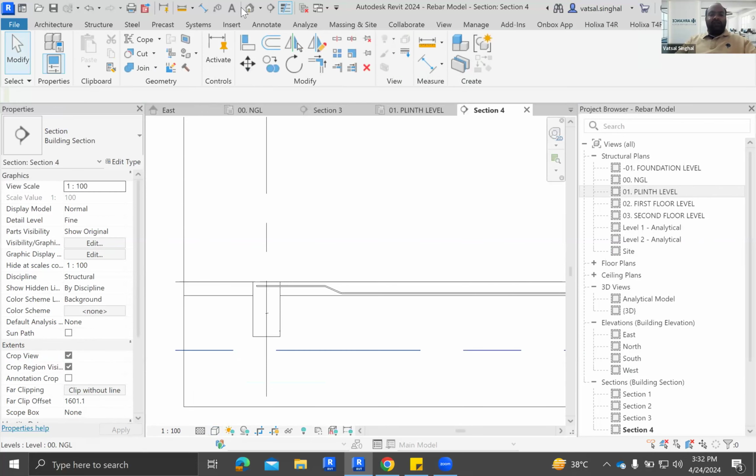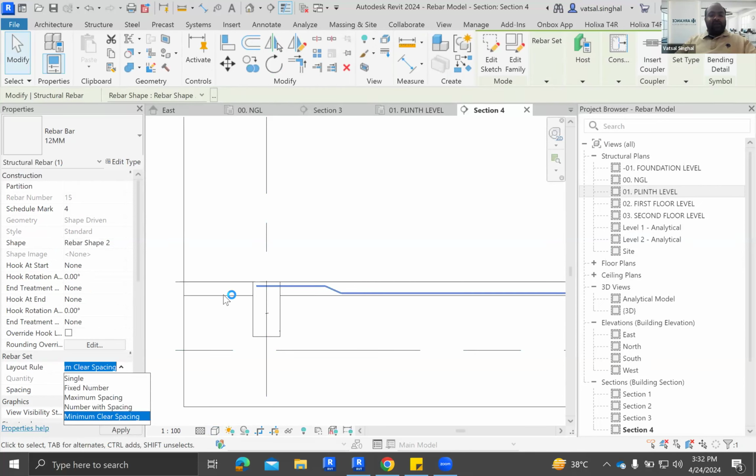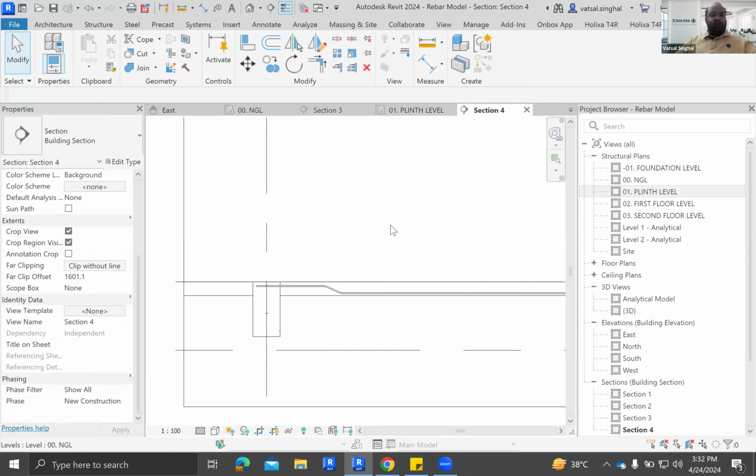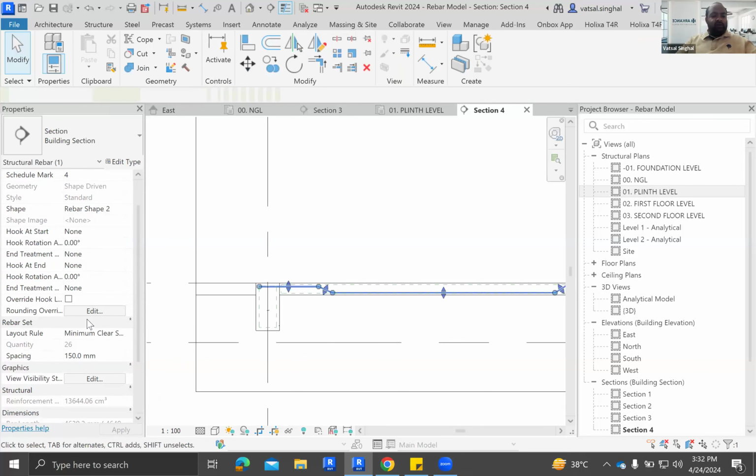You'll have to basically sketch everything, and only then you can create a one-way slab or a two-way slab. But if you just want area reinforcement inside the slab, you don't want any one-way slab, or you don't want to define any cranks. So for that, you can just directly rebar the slab as well. So I'll just select this and show it in 3D first.